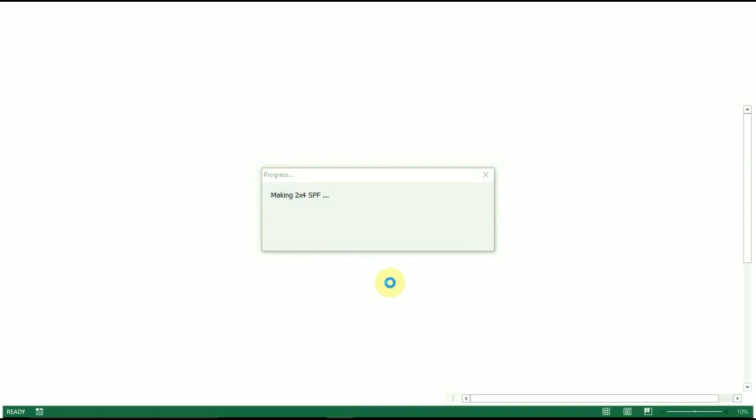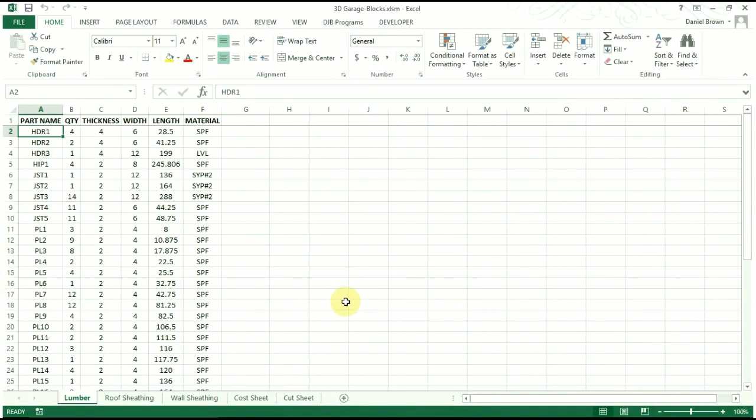So it opens up the price list database, which I'll show you here in a minute. It's got all the different materials from the lumber yard and their current prices. It takes this bill of material and gets the price for each member, and then it does an efficiency calculation based on price first. If all the parts fit on a piece, it looks at what the most efficient cost estimate is for laying out the parts on those pieces.